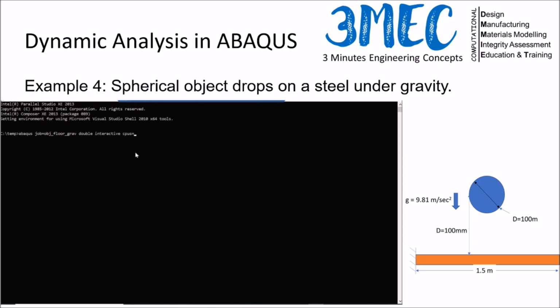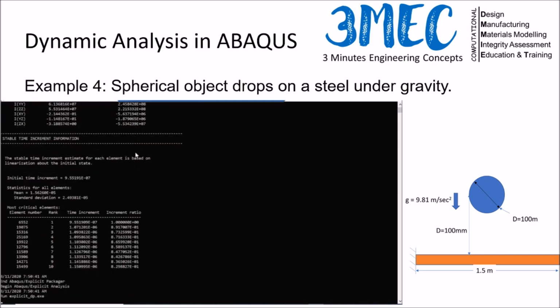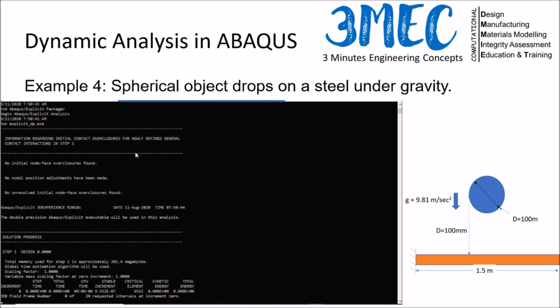And if I want to use multiple processors, I can say CPUs equals to 1 2 3 4, and also parallel equals to loop or domain, whatever. I think domain, right? I can also do data check, as there was an option in CAE, by just typing data check here. In this case, I am running it completely in a full mode interactively, so it will give me all the outputs on the screen as you see here, which is very much the same as you see in the STA file or in the status tab when you monitor the job. So now it's running.